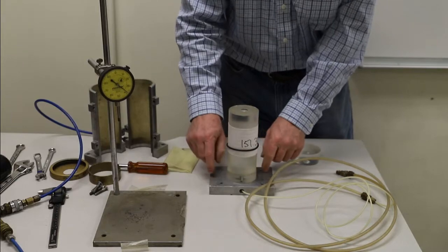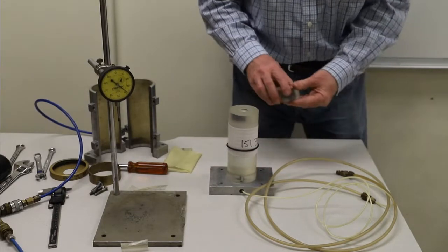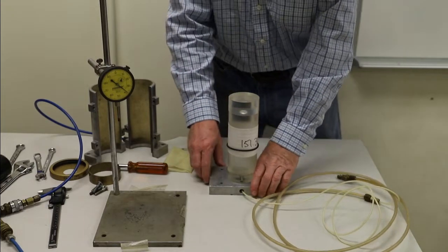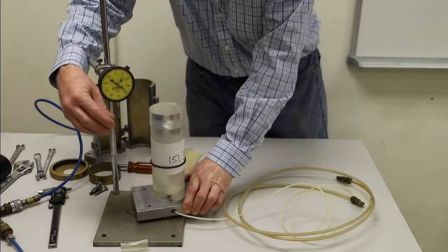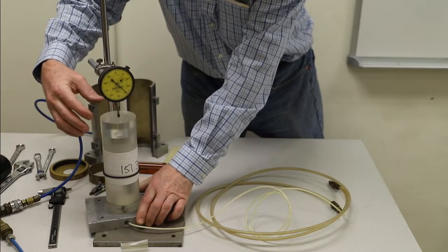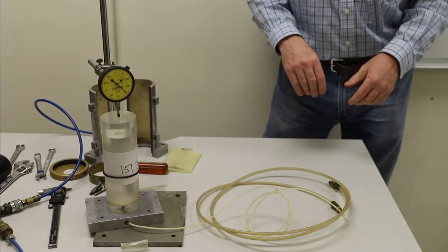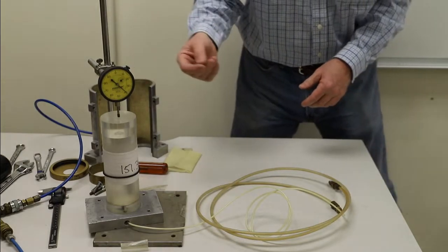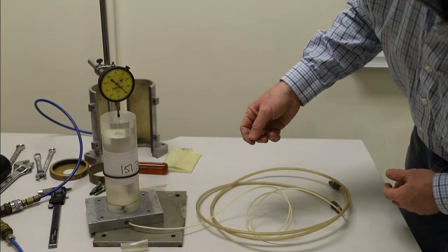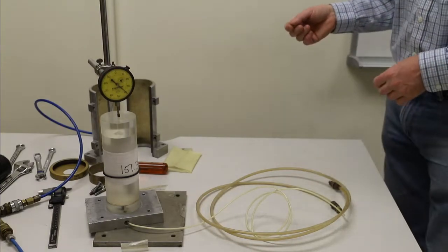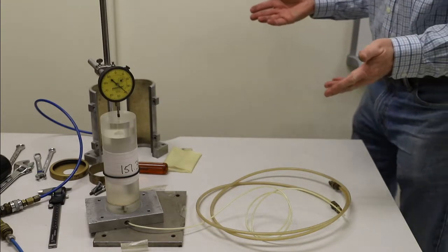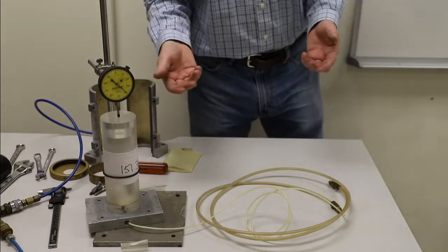If we place that on the cap that we're going to use, and we put the top cap on that we plan to use, we can put that whole assembly underneath a precise dial gauge, center it so we can have a good average value, and we're going to read some number off of this dial gauge, which looks like about 8.39 at the moment in this example. That 8.39 doesn't represent anything by itself, but it's a reference measure.